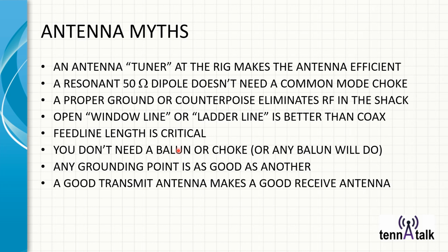A good transmit antenna makes a good receive antenna. Well, if you've got an ideal resonant transmit antenna, like an ideal dipole set up properly, it can make a very good receive antenna for that band. And not so good in other bands because it's going to tune out and reject other bands to a great extent. So no, that again is a myth.